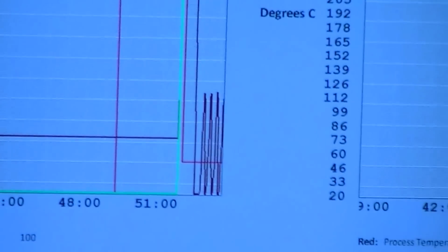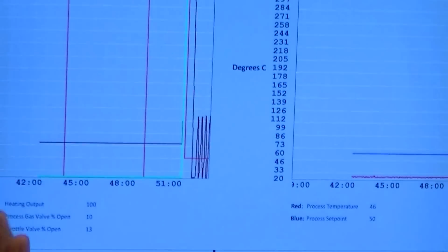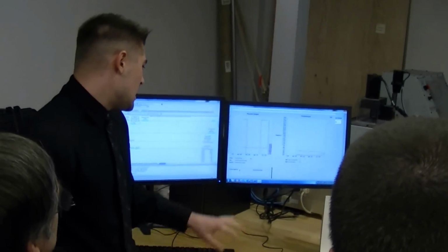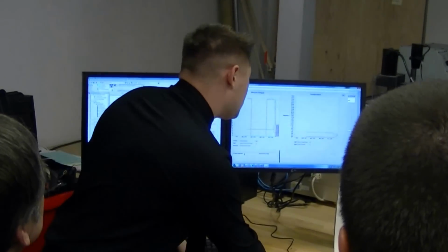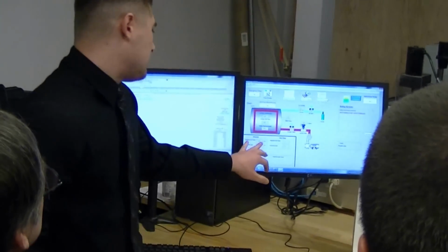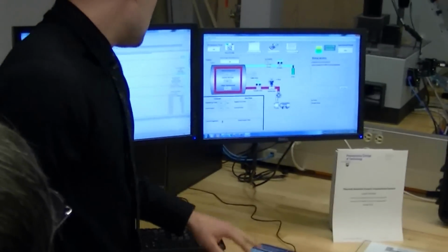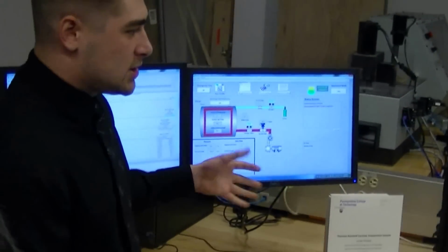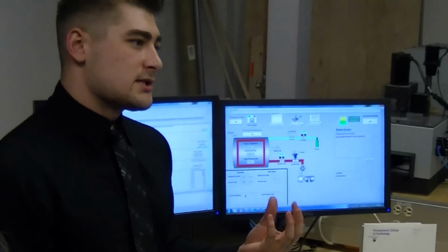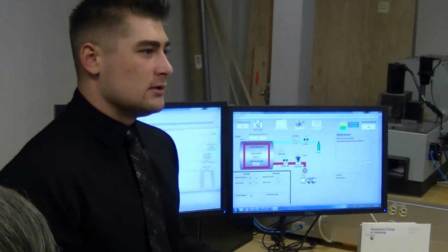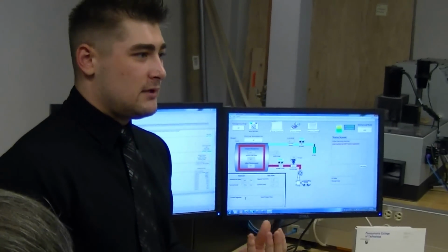The whirring sound that you hear in the variation is actually the throttle valve trying to adjust and keep that at a partial pressure of whatever the segment is. In this case, my process segment requires a pressure of 700 torr. Atmosphere is 760. Right now, the throttle valve is adjusting itself based on a 4 to 20 linear signal to compensate for the flow and the input gas as well. So it meets a constant of 700.